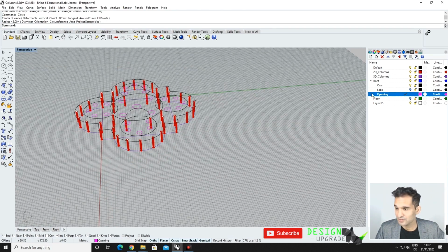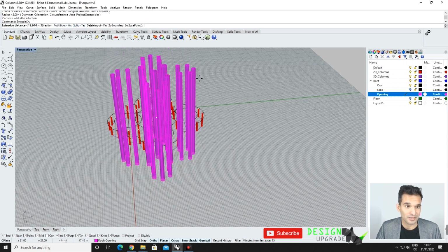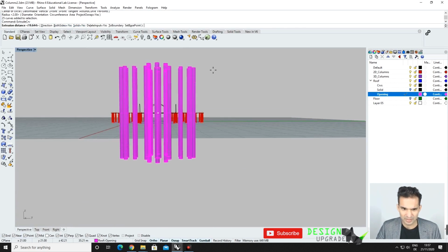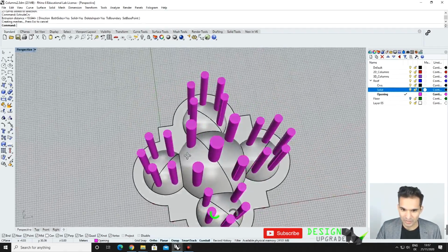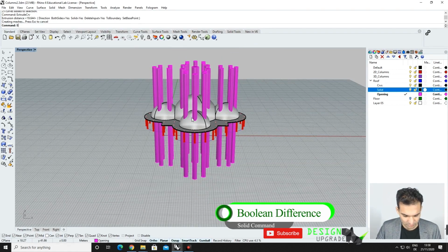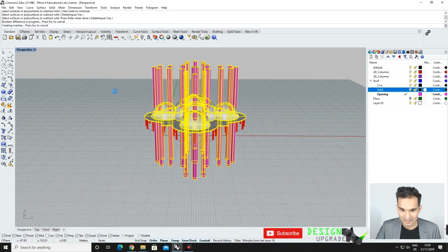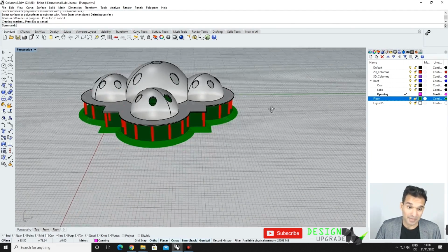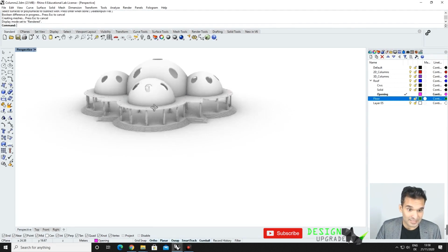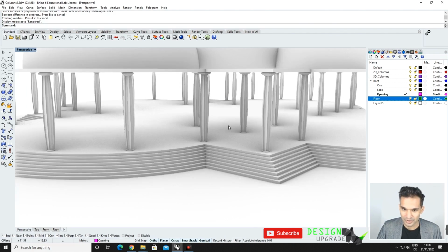The easiest thing would be now to just select these guys and just do an extrude curve. Both sides solid, yes. Just extrude extreme. So bring back our solids, and now we can create our cutouts here. Pretty much, yeah. So just say Boolean difference. This guy, difference that with these guys. And yeah, we're done. It's not the most beautiful shape we could have done, but I find it is okay to understand all the features that we have learned just to create this overall set.